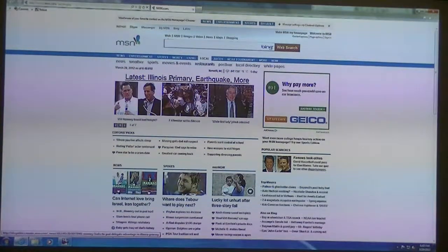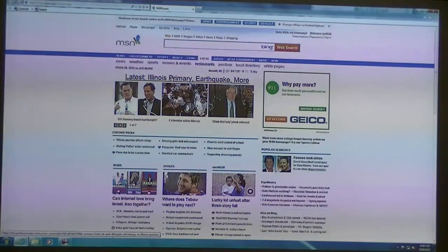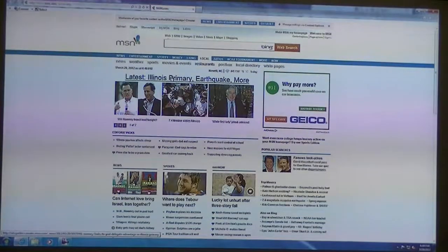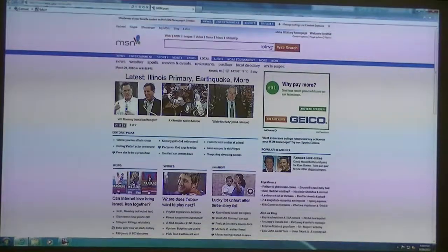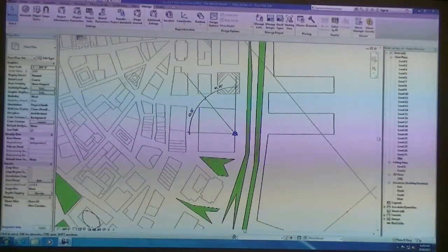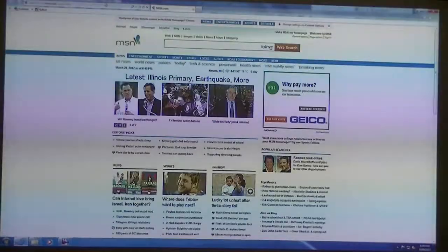straightforward, much like if you're working in Charlotte, essentially they tell you if you're on this site, your setbacks are going to be 30 feet from the front street, maybe 15 feet from the side. Your rear yard would be maybe 10 feet, and you can only go X amount of feet high. In New York, their zoning laws basically have, and let me load up that book real quick.